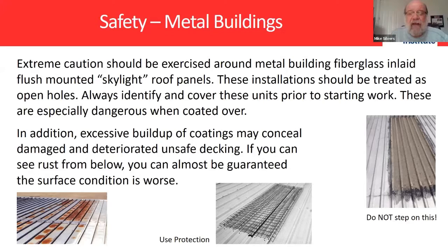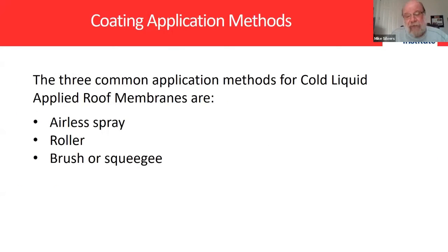Yeah, and Clay, you're still breaking up some, but guys, if you get up on one of these type roofs that usually have some skylights in them and you don't see them, be very cautious. Start looking for them, because what you may find is they're there and they're hiding from you and waiting for you to step on one of them. If you look close, you can usually tell the difference, but you've really got to look very close. So if you get on a pre-engineered metal building and you don't see skylights and it's got any age to it at all, take a real close look and see if you can figure out if they are there, and then if they are, how often and how they're spaced.